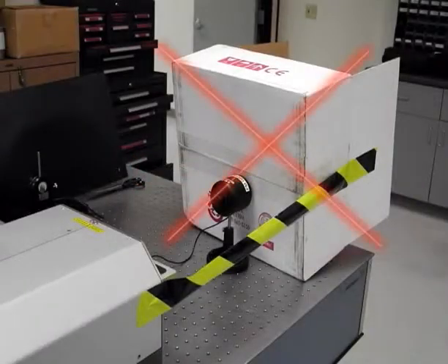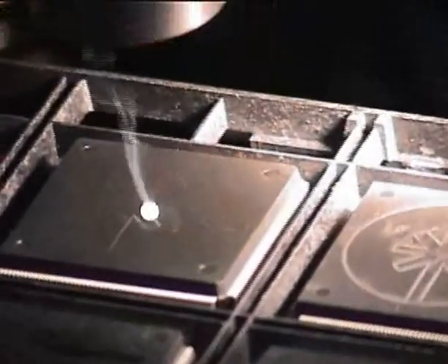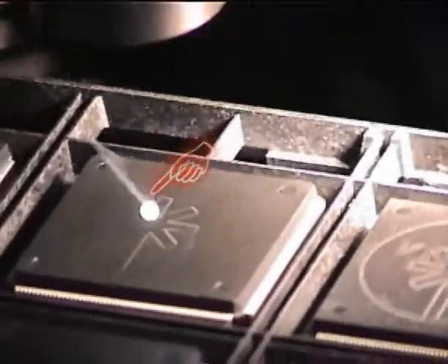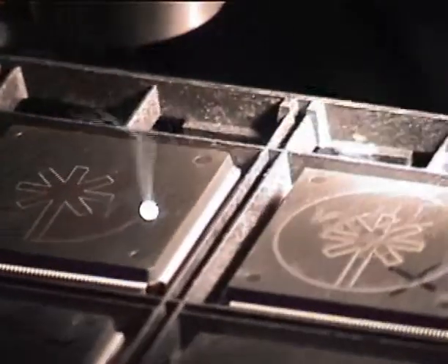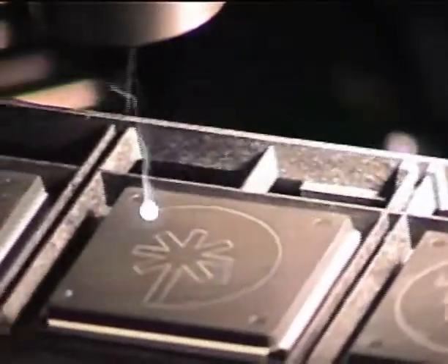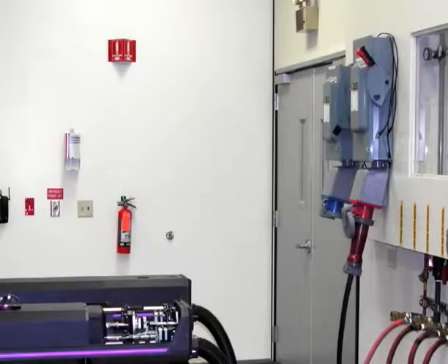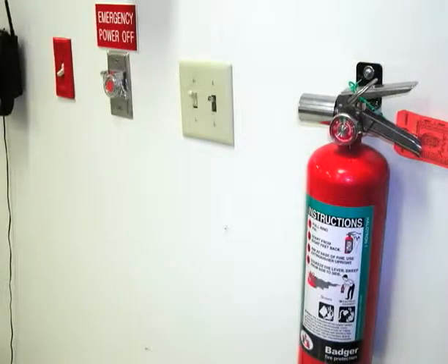The most common fire hazards are created by using improper beam enclosures that melt or catch fire, electrical circuits shorting out, and the ignition of gases from the process. To minimize these risks, make sure that you are using properly rated equipment and inspect for damage regularly. It is also very important to have a fire extinguisher device near the laser equipment. Whether it is a sprinkler system or a handheld device, be sure that it is rated to do the task at hand when called upon.